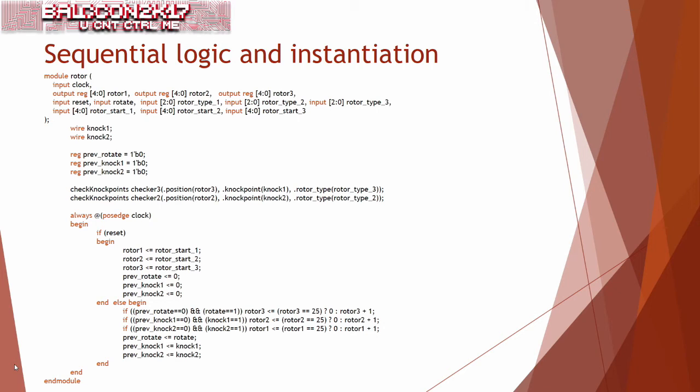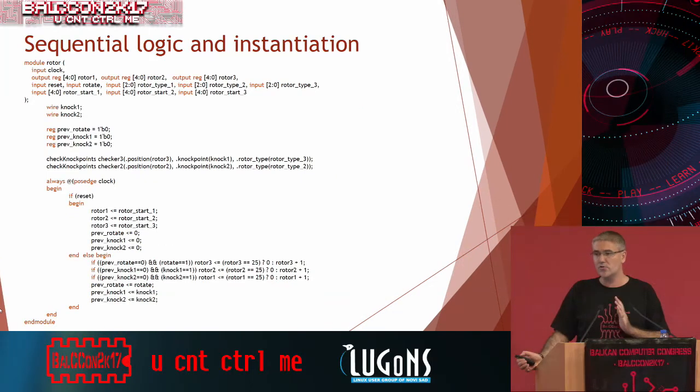Dot name of the component, and then in the brackets you put the name of your variable that is mentioned here. And here we have a clock. So we need to have a sequential logic. The rule is always keep just one. So if you're using a clock, then you should just react on the clock, nothing else.